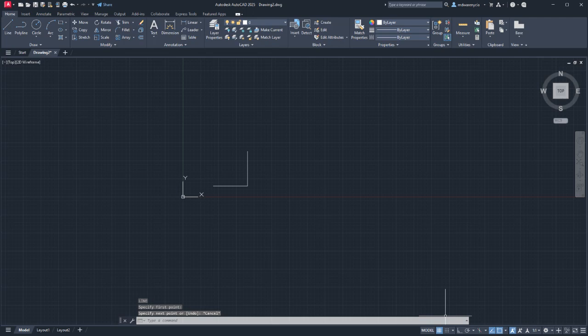Now you guys, in previous classes, I've gotten a lot of confusion with students accidentally turning this one on, which is the ortho, and this is just going to snap it entirely to 90 degrees. So again, if you know that you're going to be only working in 90-degree snaps, you can turn ortho on, but especially if you're going to end up having 45-degree angles or other stuff, you'll want to turn this off. So don't forget that you can turn these on and off as you need.